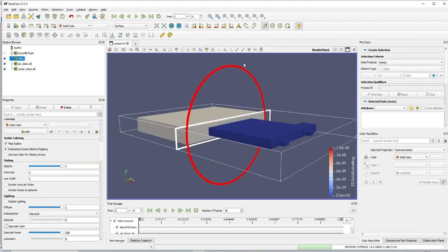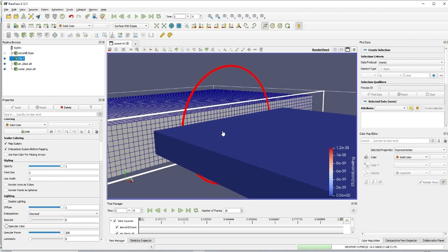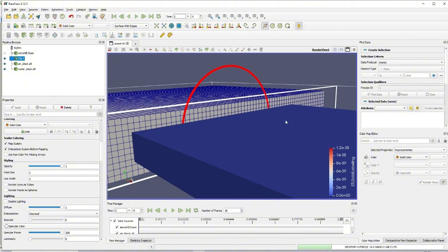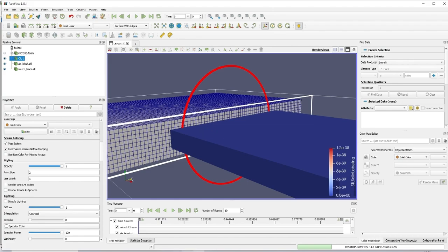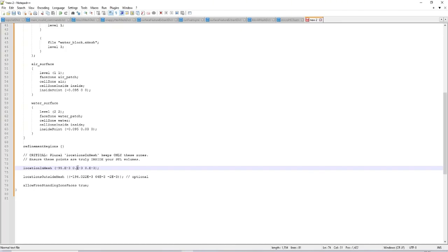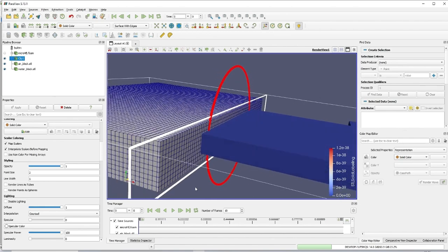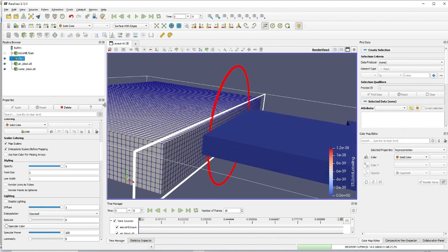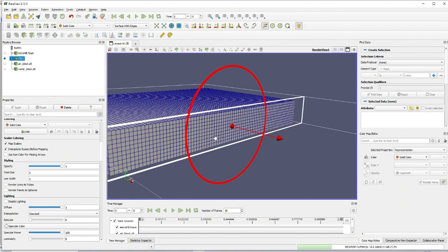I will check this, and what I'm going to maintain is the mesh around here. So I know there will be meshes, or the STL file, around here. So the X, Y will be at Y and Z 0, because they are symmetric. So Y and Z will be symmetric, exactly in the center. What I'm going to do is just make sure the X is in our region, right? So I will find some points which are mainly around here.